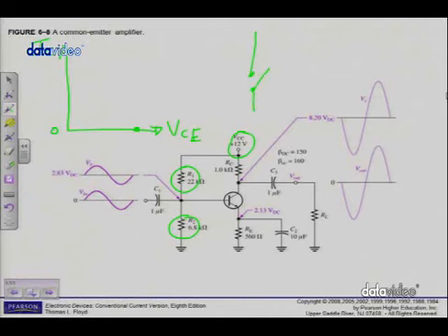Then of course there will be no current flowing through there. So IC is going to be equal to 0, but VCE is going to be equal to what? When the switch is open, measuring the supply, so I'm tracing back to the supply, that will be VCC.